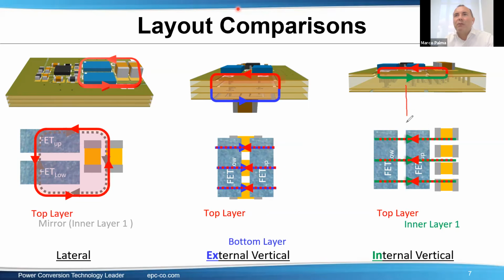I will have to put another high here, and another low here, and then put another capacitor here. You always need to make sure you are paralleling half bridges and keeping your layout, and not simply paralleling the devices and not following the main rules.